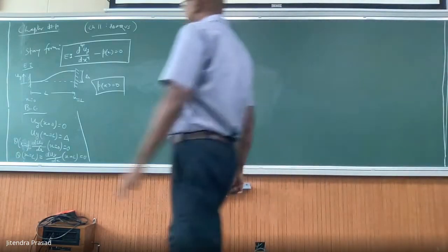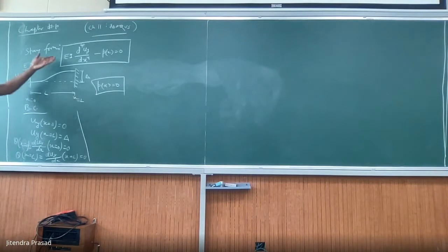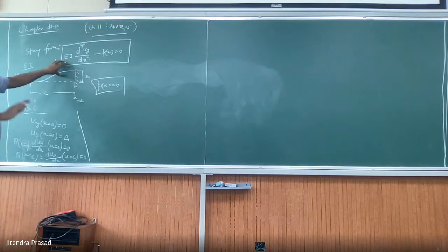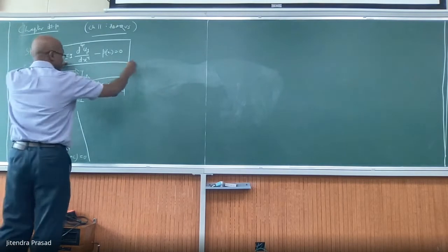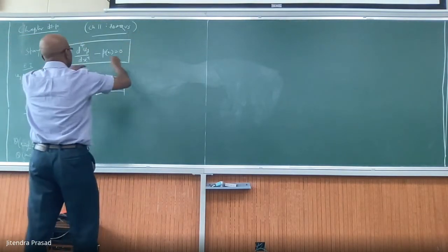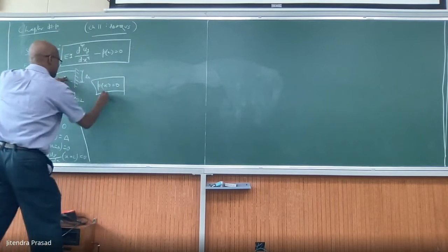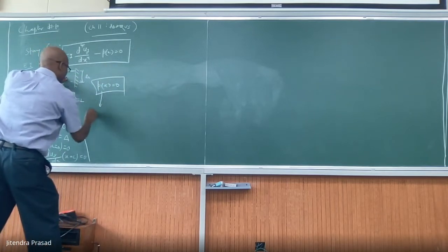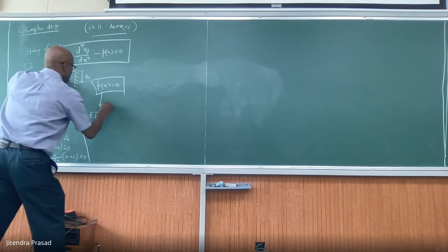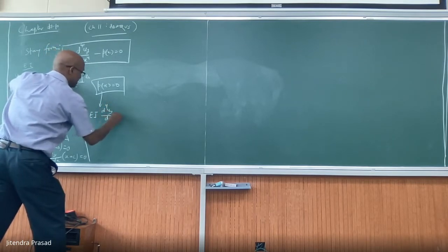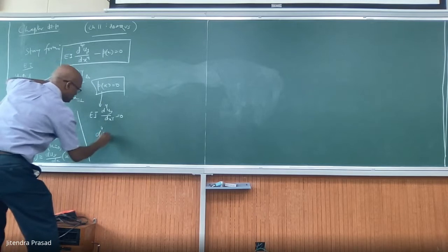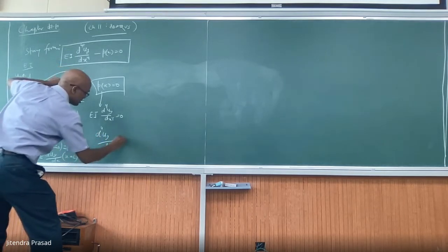So you can solve it, and it is very easy to solve. And how will you solve it? Now we are learning how to solve this. Analytically, you should be able to do it. We always try to solve analytically first, just to see how to do it. When you try to solve it, your equation is basically Px equal to 0, and that makes it EI d4 Ui over dx4 equal to 0, or simply d4 Ui over dx4 is equal to 0.